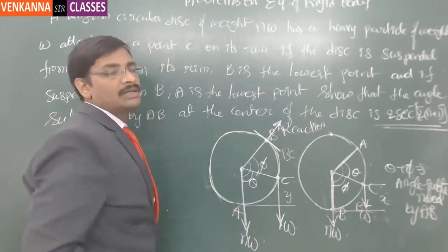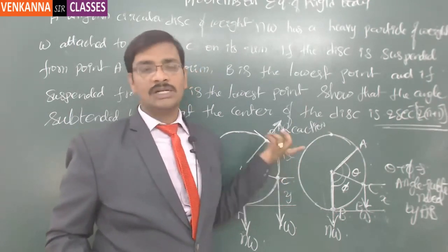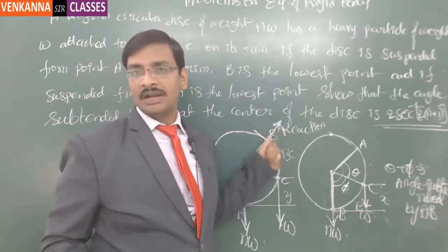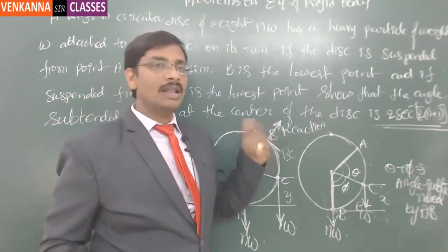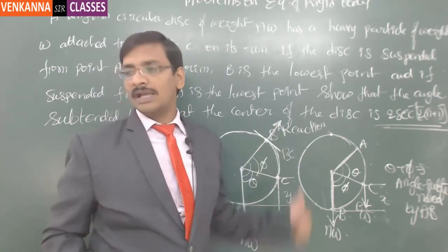Then the moment is nothing but force multiplied by the perpendicular distance from the point. So that is anyway 0. Hence, you don't need to consider the moment of this particular reaction force. Like that, you will be eliminating this particular force for the calculation purpose.